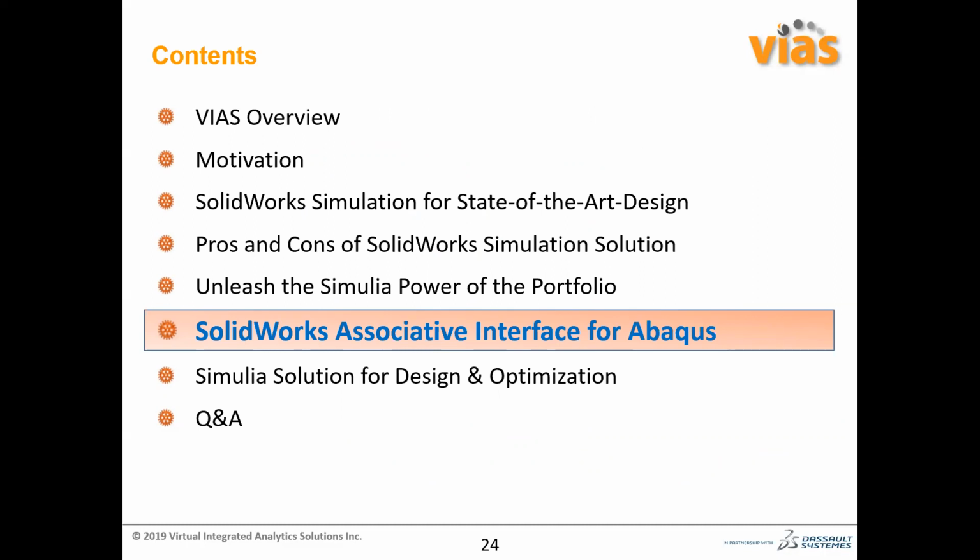Like the material response will be almost linear elastic, or the deformation is linear, and also you assume that the contact is bonded contact, or no separation contact like that. But that really does not give a better understanding of the product. That would be useful in the initial phase, but if you want to gain confidence in your product, you need to do further additional study with the advanced simulation capabilities.